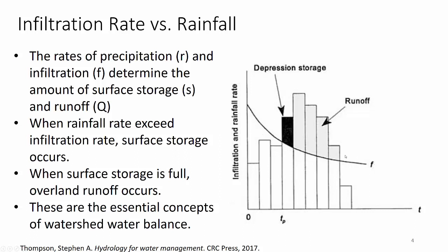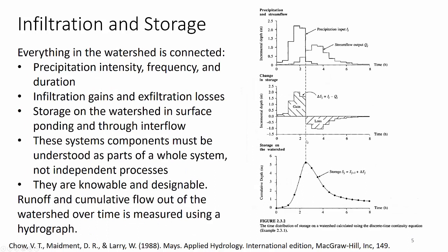So we know we're looking at runoff as part of that, the amount of rainfall that hits the ground greater than infiltration rate and exceeding depression storage. That's the runoff we're concerned about. We know that infiltration and storage directly impact runoff, especially early in the rainfall event. But as soon as those are saturated, then the rainfall becomes effective rainfall, and that becomes runoff. And runoff is really what we design as hydrologists more than anything else, either to manage it, to minimize it, or in some cases to maximize it.